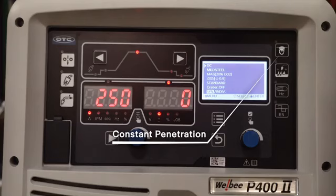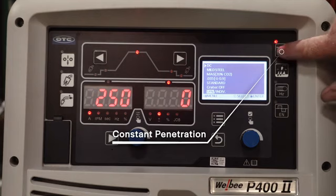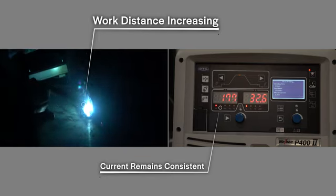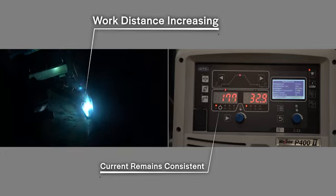Constant penetration is turned on by pushing this button on the top right of the Welbee II. With constant penetration turned on, even though my tip to work distance was increasing, welding current stayed very close to 180 amps that the machine was set at.